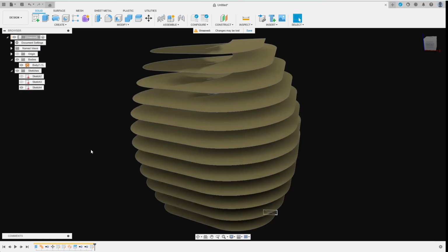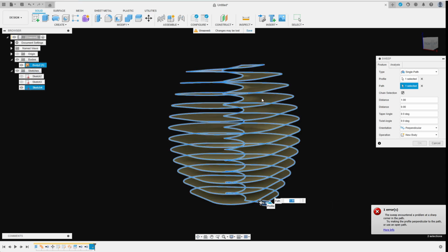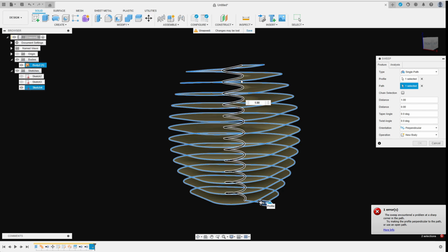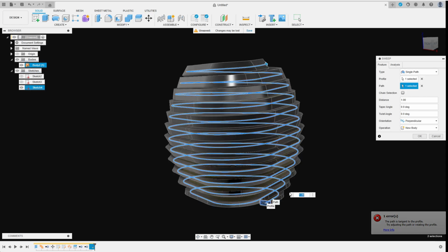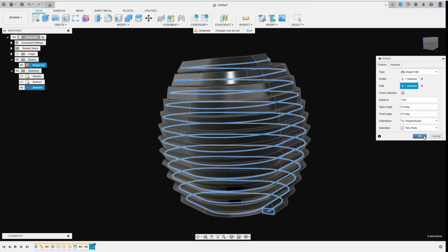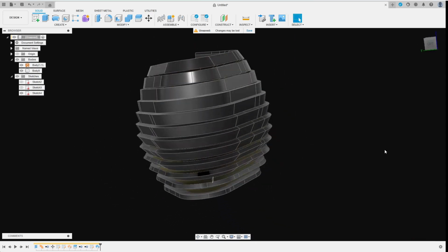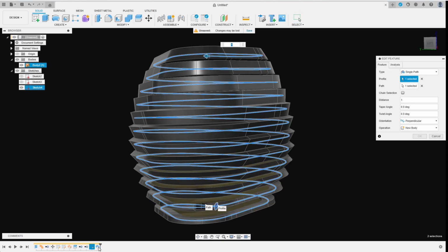Then I do a sweeping to extrude the profile I've just sketched along the outer coil edge. As before, I use the strategy to first select all edges with chain selection activated before unchecking chain selection and deselecting the inner edges. Now we can clearly see that using a single path gives a somewhat interesting but unexpected result. I want to always keep the rectangular profile horizontally oriented instead.